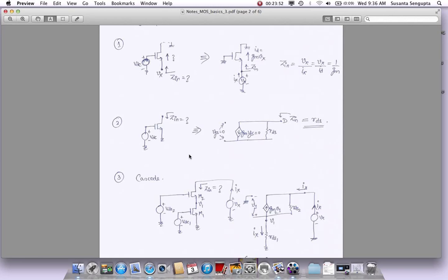I have not shown that part, whatever else could be there. So if there is a big swing going on, it gets divided by the gain of this transistor, which actually absorbs all the shock, and finally this is very, very quiet. V1 node does not see a lot of swing.